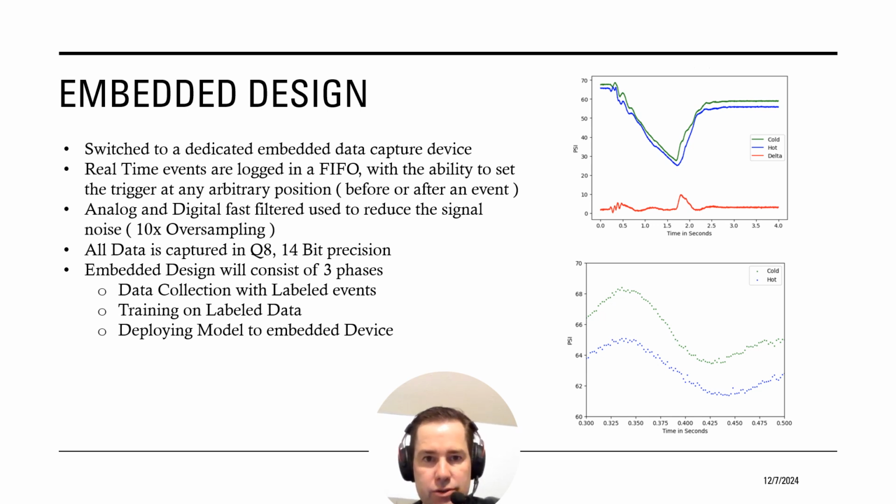This training data was saved to an onboard SD card as well as piped to a socket to my host PC. The real-time data is now accurate to the microsecond, giving me more than 1,000 times the time stability of the USB. The 10-bit ADC is oversampled 10 times, giving me a 14-bit average, which fixes nearly all of the digitization noise.